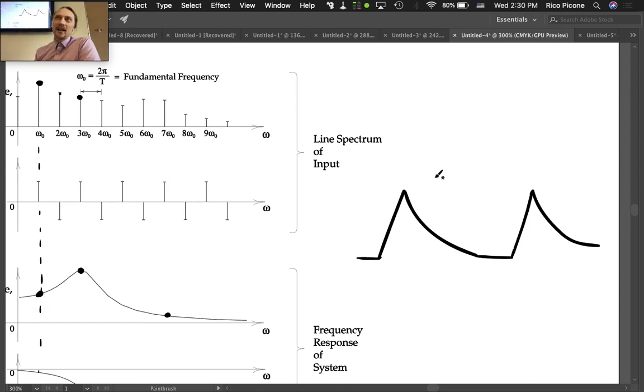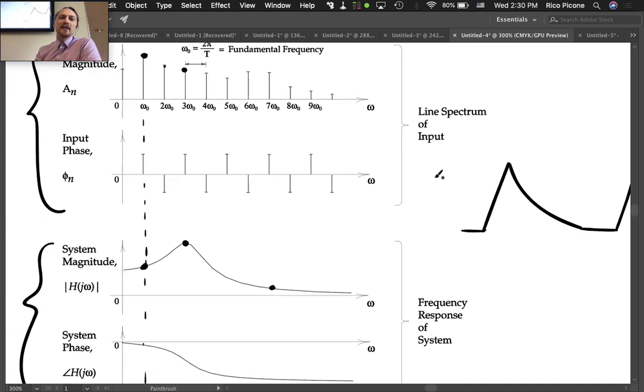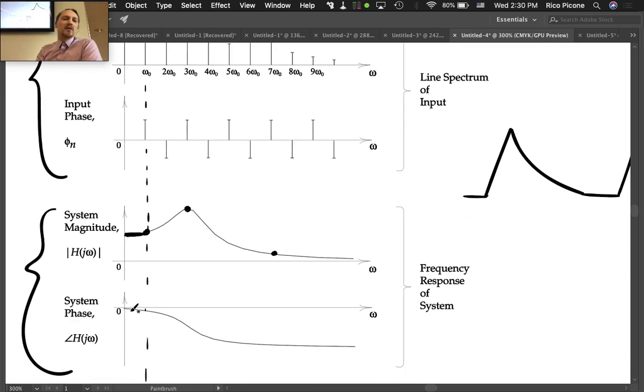And once you put that through your second order dynamic system, there's this low frequency region down here where the magnitude is pretty flat and the phase shift is pretty flat. So this is very common for most dynamic systems, especially measurement systems. It's pretty flat at low frequency, and that's where you're not going to distort stuff much. Once you get into the higher frequency stuff, you're going to start distorting.